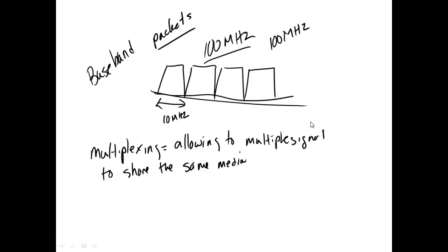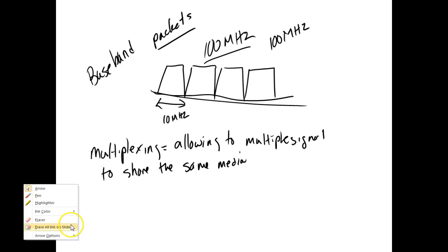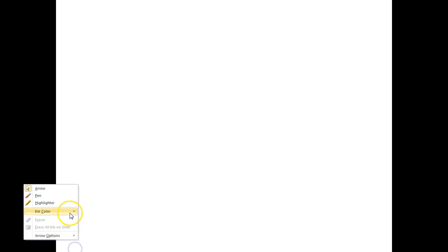So if we come up here and duplicate this, and then I put minus 12 down here and plus 12 right here, what would we have in the center? It'd be 0 volts, because these resistors right here are the same size. Everybody understand that? Yes or no? Some of y'all are looking dismayed. You okay, Joe?